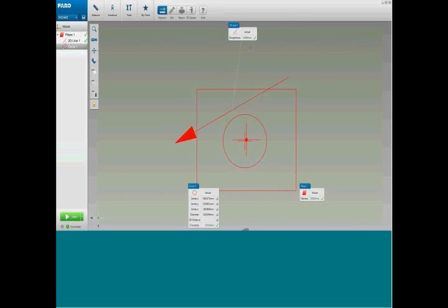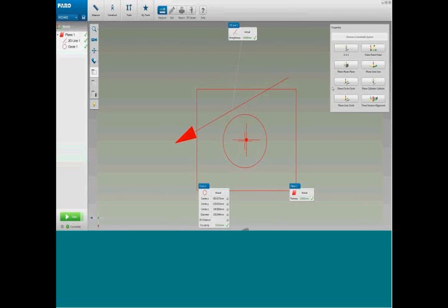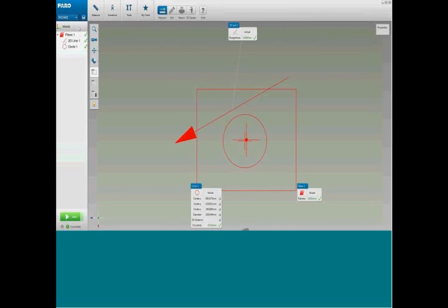Okay, so to create the coordinate system, again, I could do it via the world as before, and we have the same options as we did in basic. But this is an ideal opportunity to demonstrate a great new function within SmartInspect, the workflow suggestions. Once we have features measured or created within the feature tree, we now see a light bulb below the side panel.